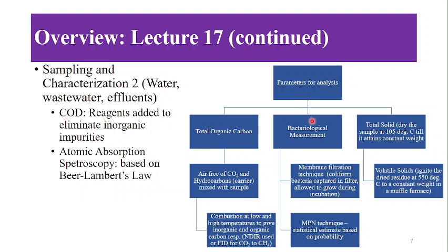Next is the bacteriological measurements. The membrane filtration technique is used here, and the coliform bacteria are captured in the filters and then allowed to grow through incubation. The MPN technique is basically a statistical method to estimate the probability of these bacteria colonies of coliform bacteria.